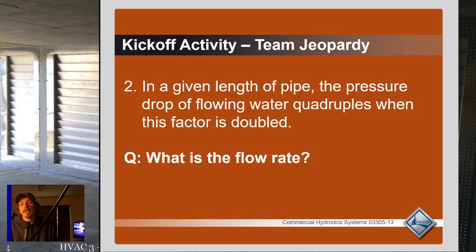And in piping and duct, we've got friction from the air or the water moving against the actual surface of the pipe, which can be pretty rough, especially when you're talking steel. And elbows and stuff cause a lot of pressure drop as well. So pressure drop is always important, and you're always trying to find a happy medium on velocity, where you're not moving too fast, but you're not moving so slow that you're making your pipe so big that it doesn't make any sense. All right, so these are all things to think about.